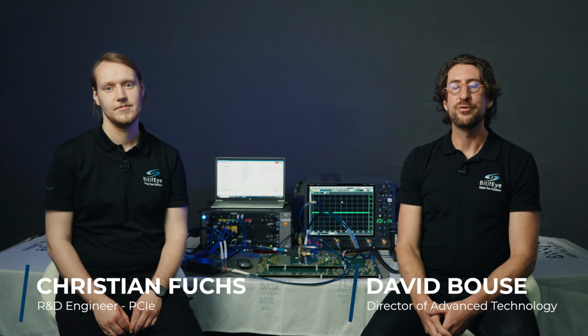Today, we're diving into one of the more challenging aspects of validating the PCI Express physical layer, specifically the electrical layer and receiver testing. As the standards have evolved from PCIe 5, which runs at 32 gigatransfers per second with NRZ signaling, or two-level signaling, now to PAM4 signaling for PCI Express 6.0, which is four-level signaling, a particular aspect of testing has gotten increasingly more complex, and we call this the back-channel optimization.